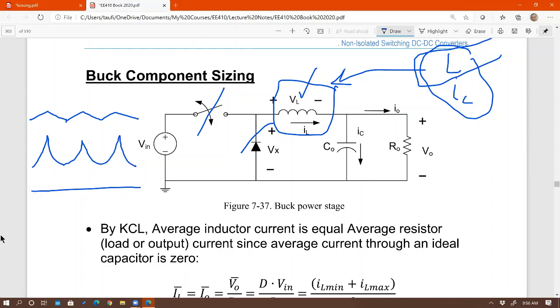They're no longer a triangular waveform. This is very high peak current, right? And that could exceed the current rating of that MOSFET or the current rating of that diode. So most likely you're going to damage the MOSFET first or the diode first before you damage the inductor.